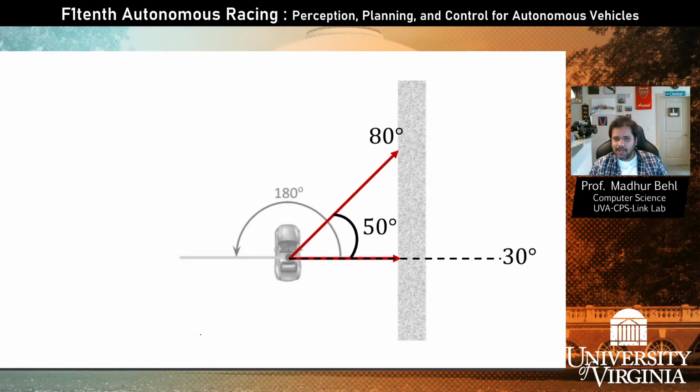So here's the same cartoon again. Let's say I have this horizontal ray, and it's not at 0 because the LiDAR field of view is such that this is actually 30 degrees. So I would pick my first ray at 30 degrees. I would pass this to get range, and it will return some value A, which is the range at this ray.